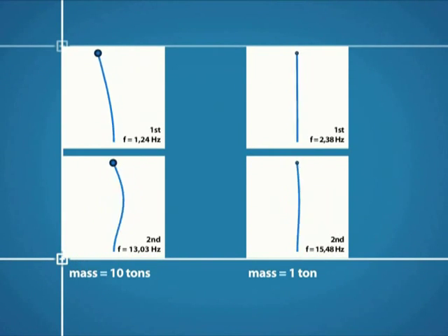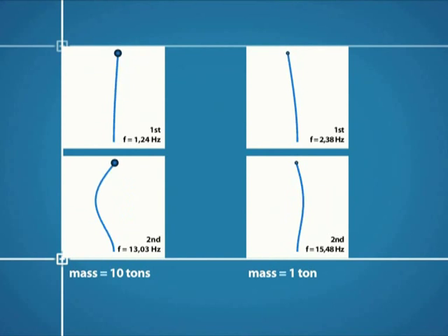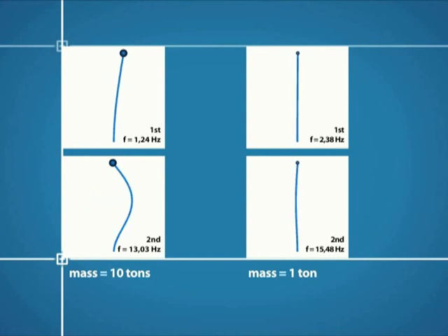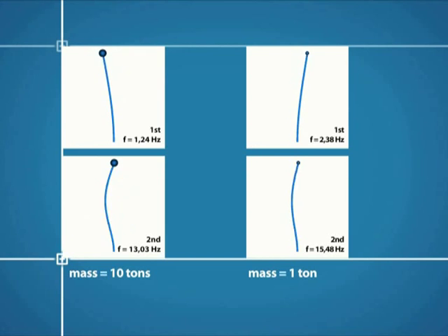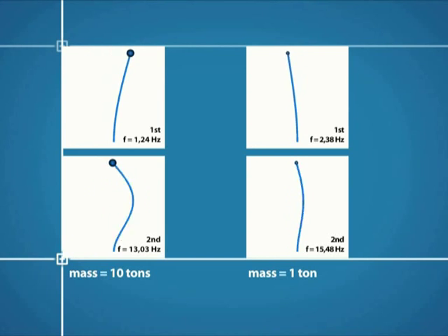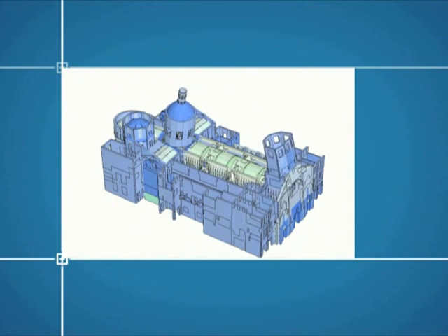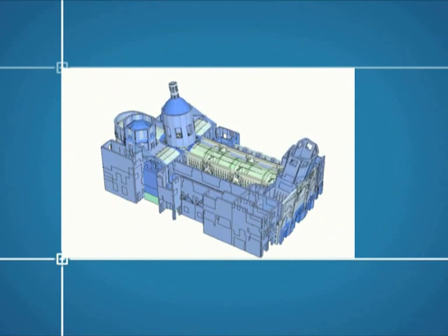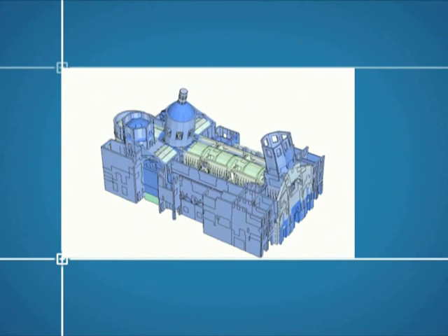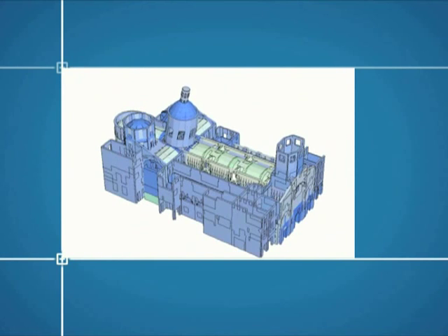Every structure possesses particular ways of vibrating, whatever the source of excitation, such as wind, traffic or seismic events, that essentially depend on its geometry, mass, stiffness and restraints. The vibration characteristics of a specific structure are a precious source of information about the physical and mechanical characteristics of the structure. Ambient vibration tests were thus performed to define the dynamic response of the Qutub Minar.